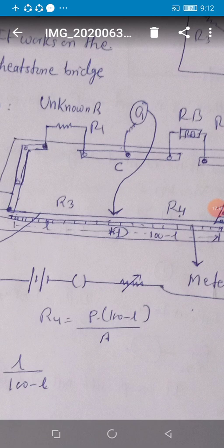So what you have to do is, first, where I have written R1, you have to connect one resistor whose value you don't know. Even if you know it, it is a written value, so you calculate R1. Say I have given an example, R1 is suppose 3. You connect R1 as 3 ohm there. You calculate the value of R1 experimentally. It will come out to be near about 3 only.